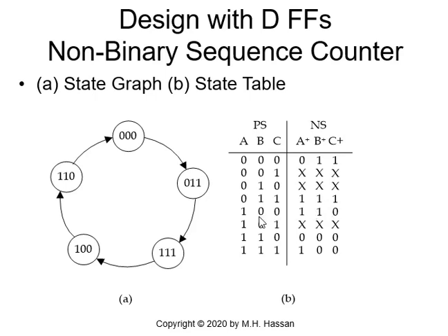If I am in state 100, where is 100? It's right here. The next state is 110. 100 goes to 110. If I am in state 101, we say don't care. If I'm in state 110, the next state will be 000. If I'm in state 111, the next state is 100.